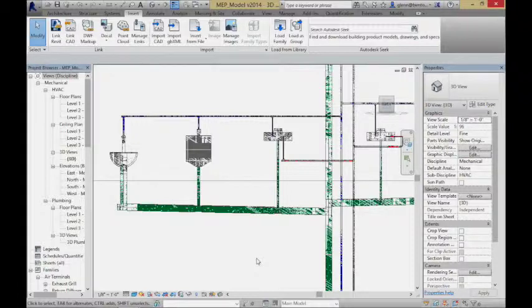On the other hand, the water systems are a little bit easier in terms of the water supply. Toilets and urinals just have to be supplied with cold water. That can tend to be a very small line, like an inch line or a half-inch line. It just depends on how much flow you have to provide. Sinks have even smaller lines. It tends to be only cold water and hot water.